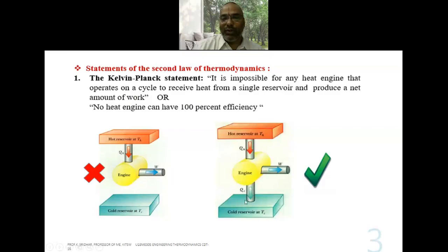That is a limitation. Here you can see very comfortably a heat engine. It is a work producing device. Under what circumstances will the heat engine produce work? Here is the high thermal energy reservoir, the hot reservoir, which is known as the source, available at the temperature TH, the temperature of the hot body. And another thermal energy reservoir is the cold reservoir, which is also known as the sink. The sink is maintained at TC, the temperature of the cold body.